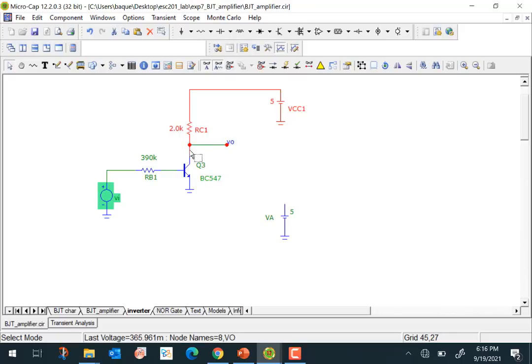So for example, let's say the node is at 5 volt, and when you switch the input from 0 to 5, the output has to go from 5 to 0, but there's a capacitance that has to be discharged. And if you don't give enough time, it may only go from 5 to 4 volt and is still high. And therefore you didn't give it enough time to go to 0, and therefore it didn't go to logic 0 here. So all of these circuits will fail beyond a certain frequency. And that is all happening because of the internal transistor capacitances.